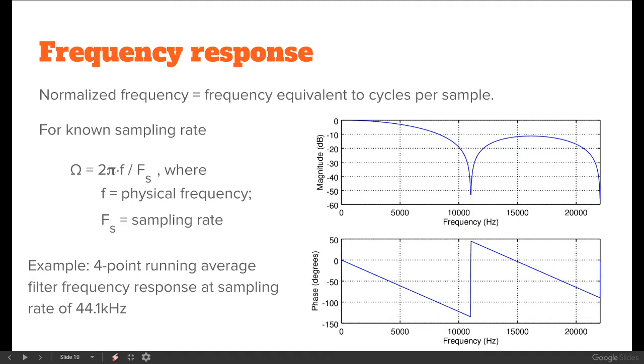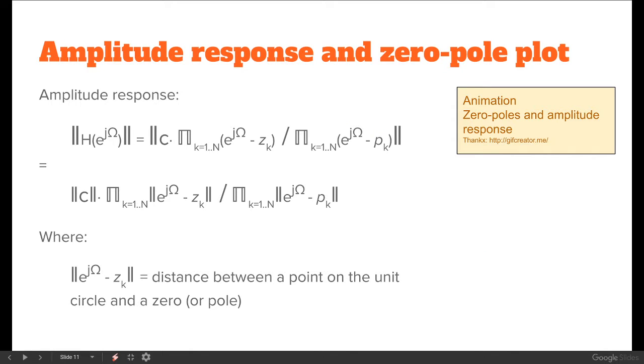It's not really a good filter at all. 4-point running average. Actually, the running average filter is not a good filter at all. It's just easy to calculate, but crappy. Don't use it ever again. It doesn't even suppress noise.